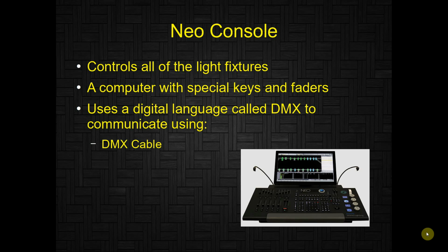Now, in recent days, because of advances in technology, it used to always be DMX cable, but nowadays you may find some that are sending out the DMX information over Cat5 or Cat6 cable, and even Wi-Fi. Some of the newer fixtures that are coming out have built-in Wi-Fi. The lighting console with a Wi-Fi attachment on it can send DMX information via Wi-Fi up to the light, so now we totally eliminate the cables. That setup makes it a lot easier because now we only have just a power cable and it's getting Wi-Fi information. I'm thinking at the school though most everything is going to be connected by DMX cable since it's a little bit of an older system.